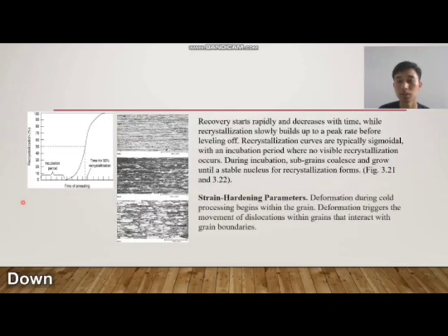Next, recovery starts rapidly and decreases with time, while recrystallization slowly builds up to a peak right before leveling off. Recrystallization curves are typically sigmoidal, with an incubation period where no visible recrystallization occurs.